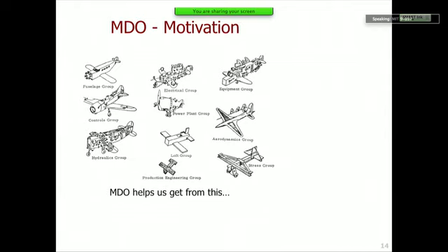The aerodynamics group wants a very nice high aspect ratio wing, very thin, very low drag. The problem is there's no room for passengers or cargo here. You see this? The stress group has a nice wing in the shape of an I-beam. I-beams are great, this is good if you're a civil engineer, but not so much here. None of these things would work on their own.